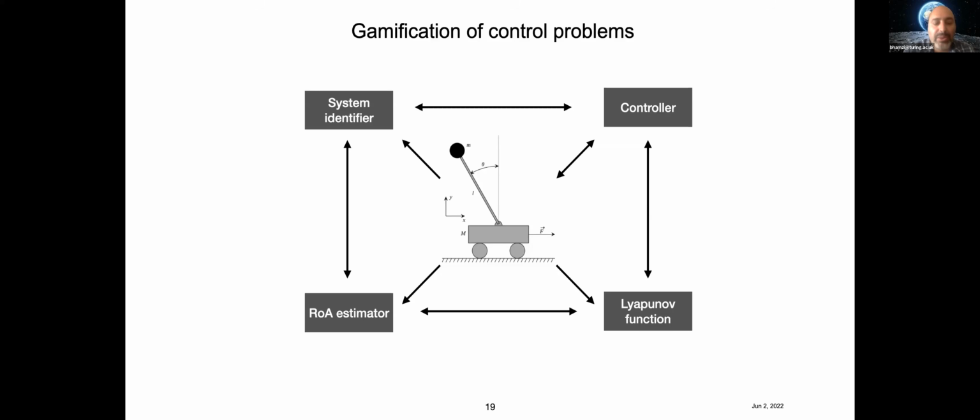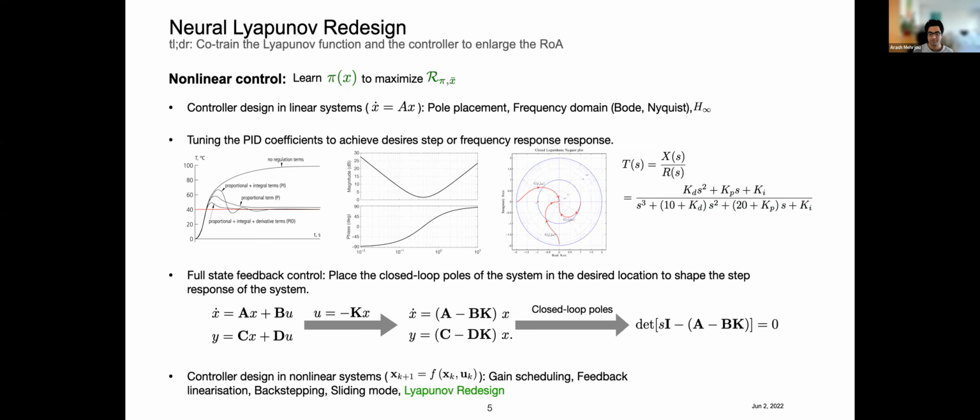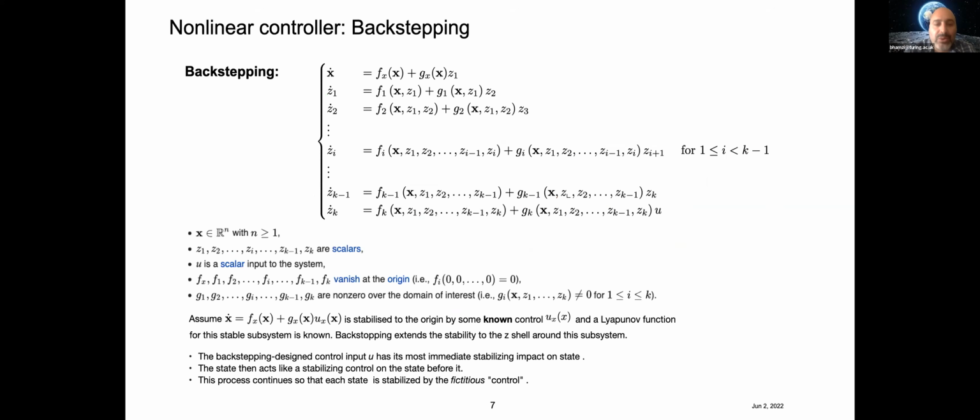I have a question about, for example, if you come back to backstepping. Did you apply this to the context of backstepping, where you construct the Lyapunov function for the first level, and then you propagate and see what happens? The advantage of backstepping or feed-forward structures is that you have some analytic results. So did you try to apply it to cases where it's upper triangular or lower triangular, and get analytic results for your method, or no?